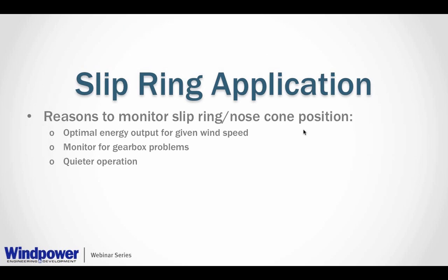So in the blade pitch application, just to summarize, there's two approaches, absolute and incremental, and we believe incremental is more durable. And we'll talk a little bit later about some features about incremental encoders, about how you can get a more reliable incremental encoder as well. We also believe putting the encoder behind the motor is more durable, particularly when you talk about that small encoder with a small bearing hooked to a big plastic gear. It's just really vulnerable versus that durable solution we showed you earlier where it's mounted behind the motor.